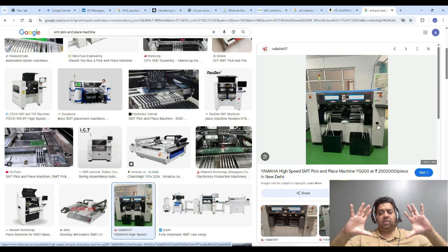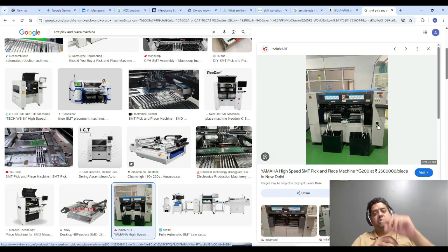Now, if your PCB is about this big, let's say you have 100 different components, right? You want to make sure that, well, there is an engineering behind which component goes first and which goes second and which goes third. The engineering is, well, one is path optimization. You want to make sure that if you place a component here, you're not going to place the second one here and then the third one here and the fourth one.